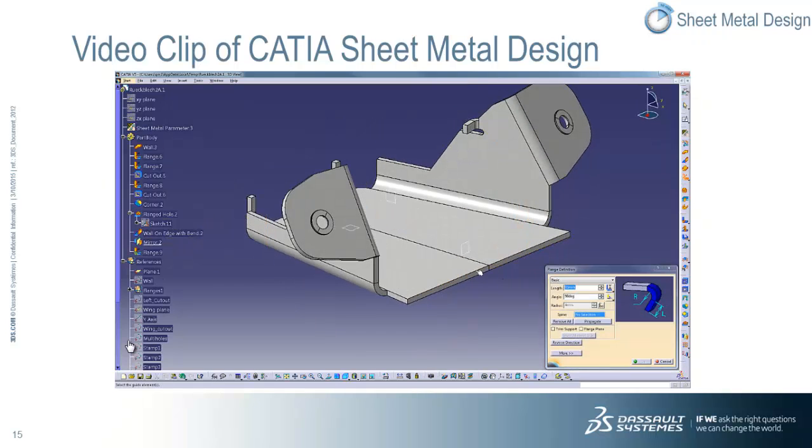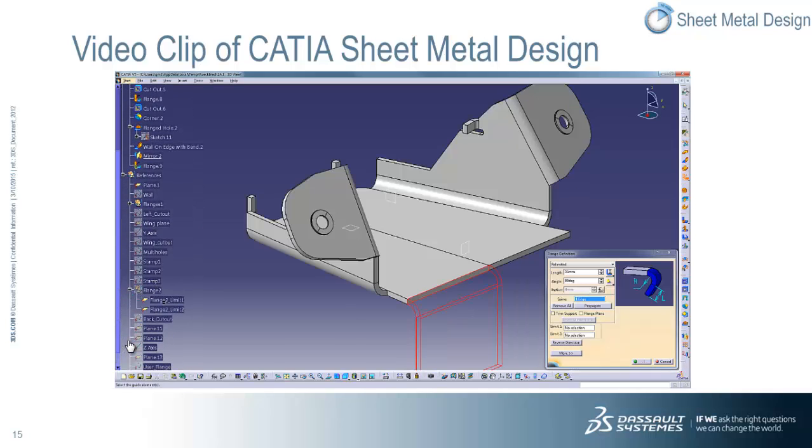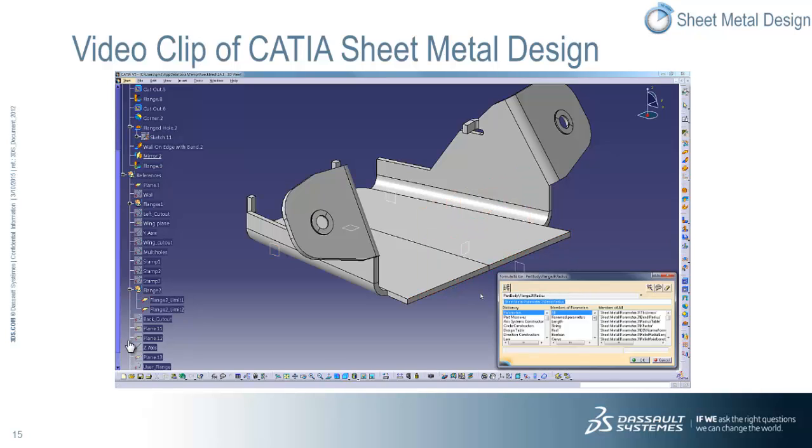Using the mirroring capability, we instantaneously define the other side of the sheet metal part. And again, we view the folded and unfolded representation of the part. We then create another flange using some profiles to define the limits, and then another cutout area using two more profiles to generate the precise flange shape that we want.